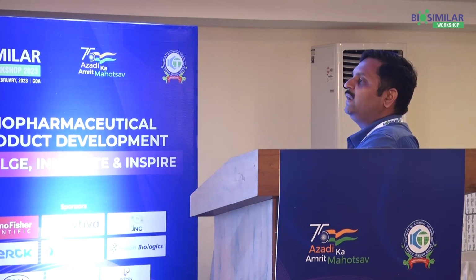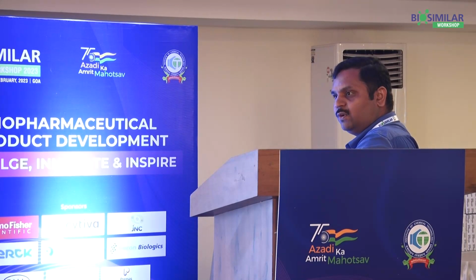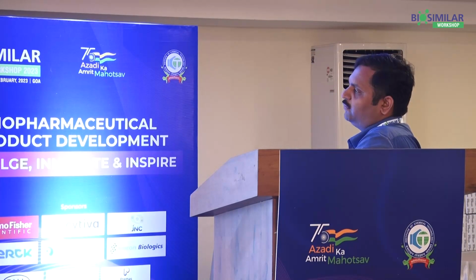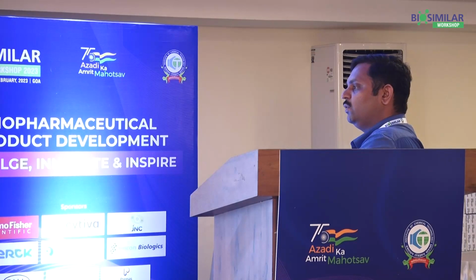So the concluding statements are here: a mechanistic model-based approach was used for development of the twin column setup, and it is working fine. Various parameters like breakthrough curves were predicted, and we have also understood the impact of productivity and capacity utilization based on prediction. Based on this, we have identified that feed concentration, residence time, and breakthrough loading are definitely going to impact the continuous process. And based on the modeling, we can select the operating window which is feasible, and that can be validated based on the experimental data.